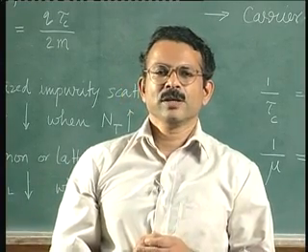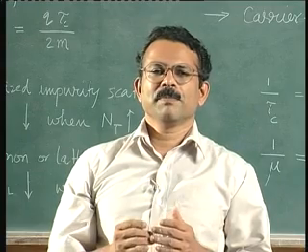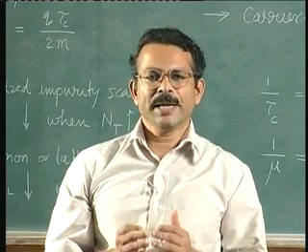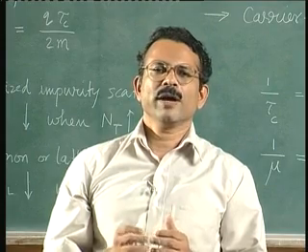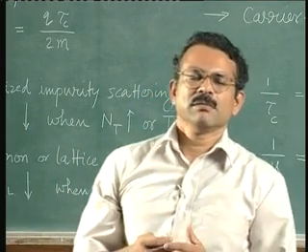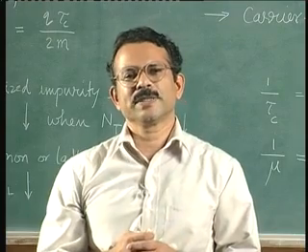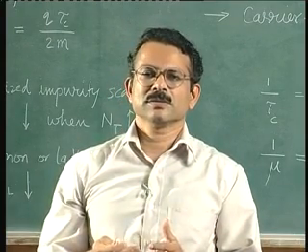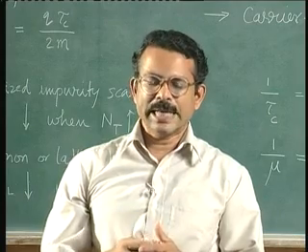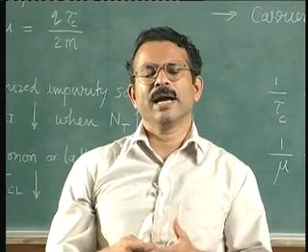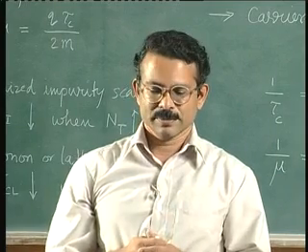So if you have bipolar transistors such as NPN transistors, or field effect transistors, you cannot say MOSFETs because it is difficult to make MOSFETs in gallium arsenide. Field effect transistors which depend on electrons, that is n-type field effect transistors, in gallium arsenide can carry more current and will be faster than in silicon.